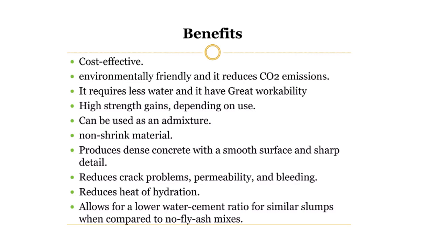It requires less water and has great workability. High strength gain depending on its usage. It can be used as an admixture. It is a non-staining material. Produces dense concrete with a smooth surface and sharp detail. Reduces crack problems, permeability and bleeding, reduces heat of hydration, allows for a lower cement content for a similar slump when compared to no fly ash mixes.